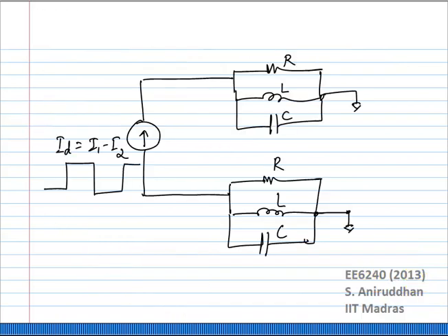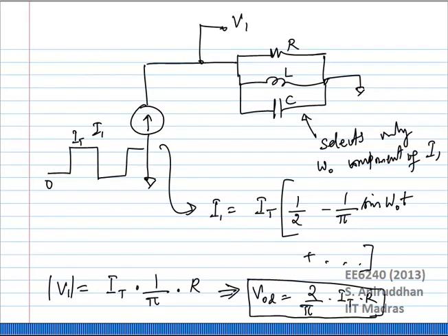And the real equivalent circuit of the oscillator, of the cross coupled portion, is going to be this. It is going to be a current source which is switching from minus IT to IT, flowing into the RLC tank. What we did was, we took one half of this circuit, so that is going from 0 to IT, flowing through this RLC to give you this voltage V1.